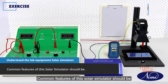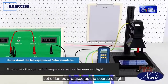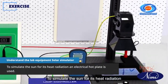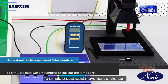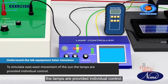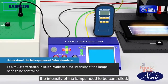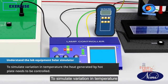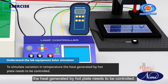Common features of this solar simulator should be: to simulate the sun, a set of lamps is used as the source of light. To simulate the sun for its heat radiation, an electrical hot plate is used. To simulate east-west movement of the sun, the lamps are provided with individual control. To simulate variation in solar irradiation, the intensity of the lamps needs to be controlled. To simulate variation in temperature, the heat generated by the hot plate needs to be controlled.